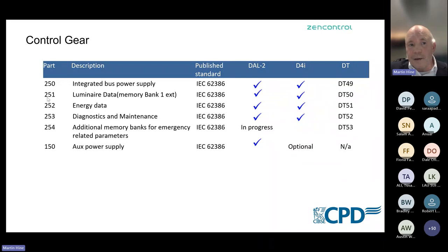So these areas are specifically useful when you look at the Part L 6.6 requirement. Where there's a metering or sub-metering, there's also a clause in there that says that you can actually monitor the data from the luminaires via the lighting control solution. This is possible now with the DALI 2 drivers that are providing this real-time information direct from the drivers.